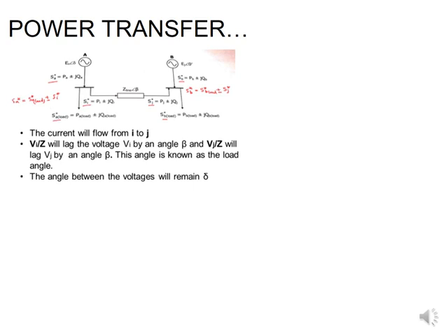And then you can see that at EJ, I've got my angle to be sitting at 0, and EJ is at B power station. So it means that my A is my leading voltage and my B would be where my lagging voltage at EJ is going to be at.